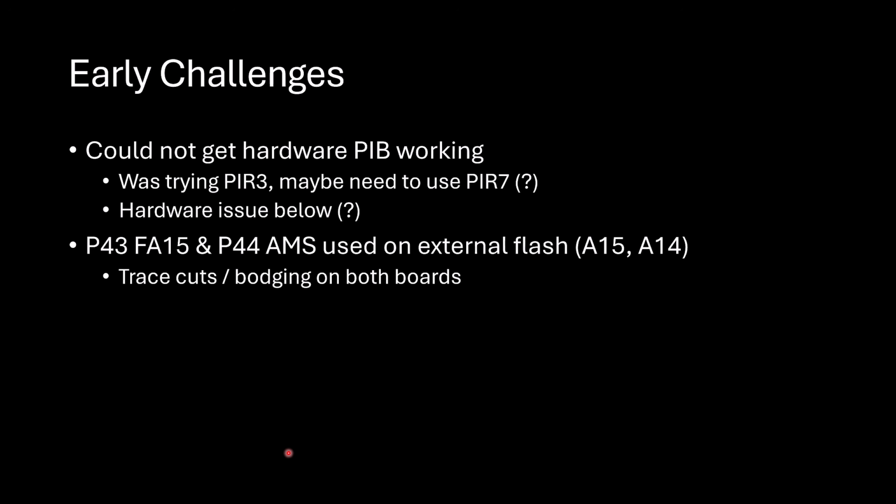But if all of a sudden I start writing to pins 43 and 44, like I drop 44 low, that just told the flash to jump to a different section of flash. And that will instantly halt my program. It'll stop it because it jumped to a different spot of flash, which is probably all Fs, and I'm not going anywhere at that point.